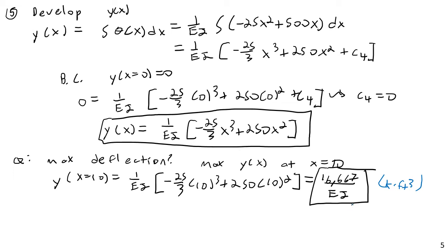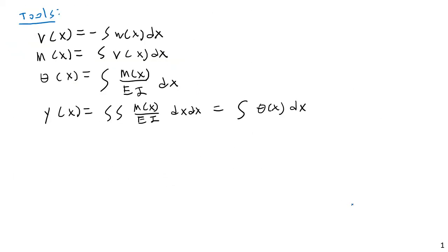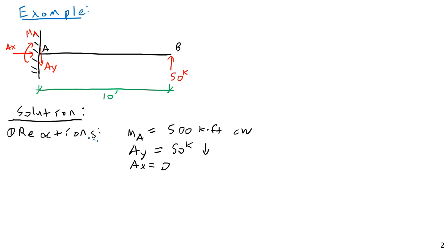So if you're working through problems like this, it would probably behoove you, if you really want to avoid doing a lot of conversion, to do the whole integration with a beam length of 120 inches instead of a beam length of 10 feet. That's kind of a foolproof method for this, and it's probably the simplest way to do it. When I need to work through a longer one by hand, that's what I'll do myself.